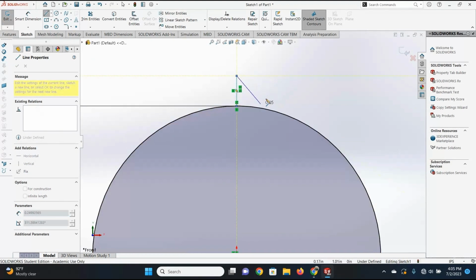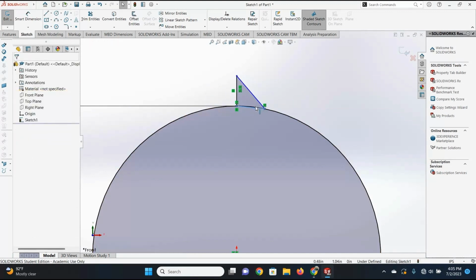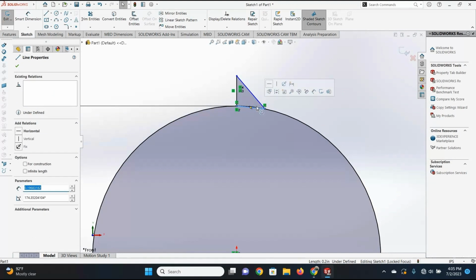For me to get rid of this line, I have to click like that and end it, because if I hit escape, it will end my current recording. But normally you can just click escape and it will end your line right there. But now I can hit X and then go ahead and select these lines and delete them.